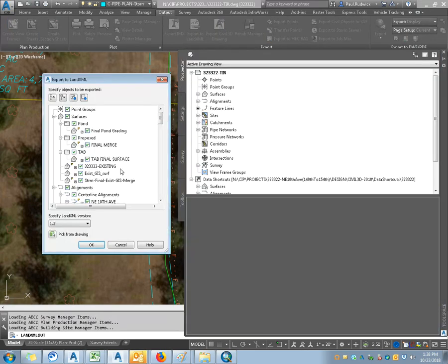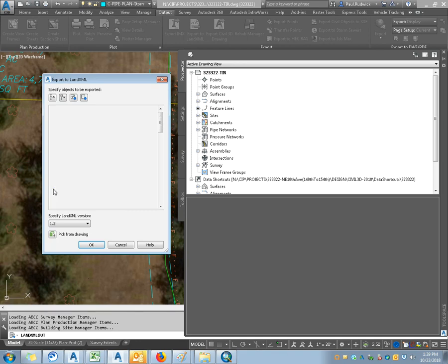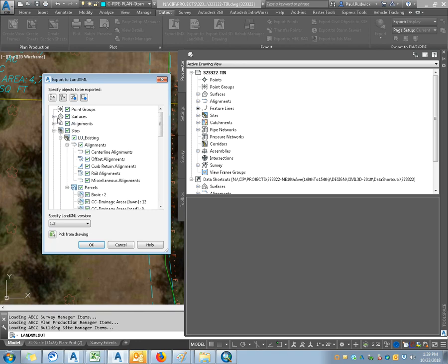And that basically lets you pull any bit of data that is able to be written into a LandXML. So that's almost all Civil 3D objects. Surfaces can't be read by SSA, but the data would be in the file. Alignments, same thing. And then within these, you can see I've put in some of these land use basins.